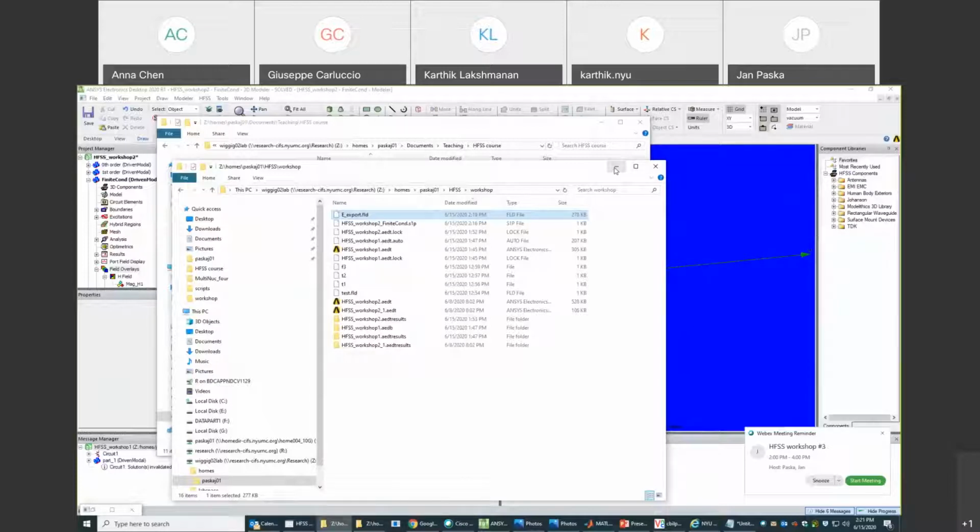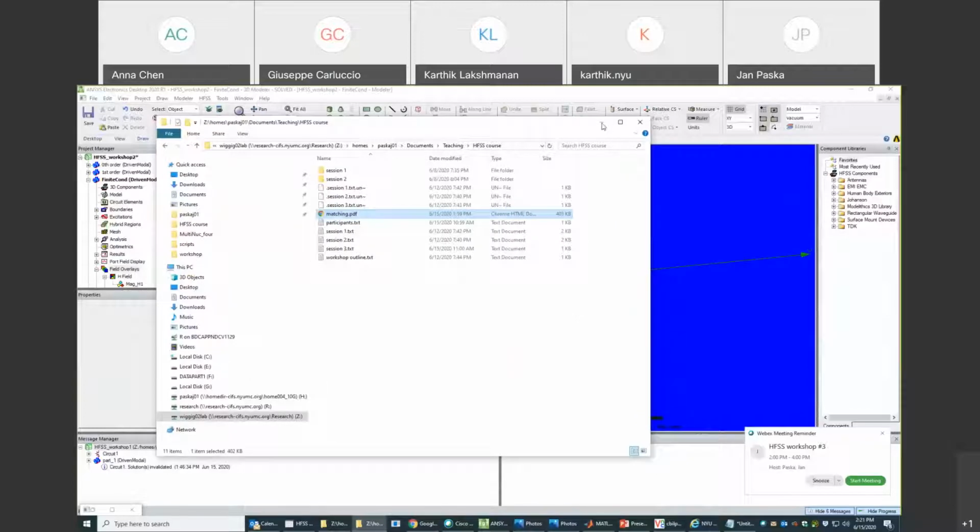But HFSS has a tetrahedral grid, and you want to export on a Cartesian grid, so you need to interpolate the field values at each point that you give in. So that's why it can take a long time if you are exporting on many points. But eventually you will do it. If you have many points, then maybe try to export it overnight.